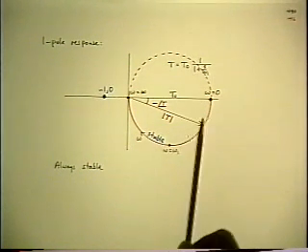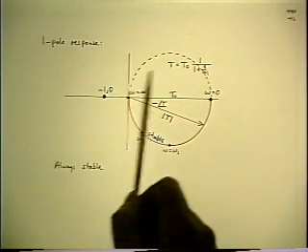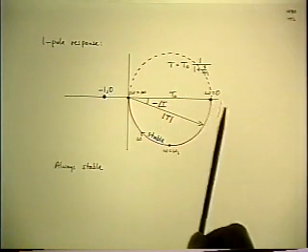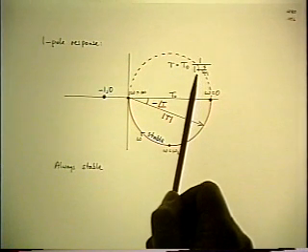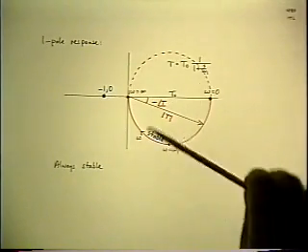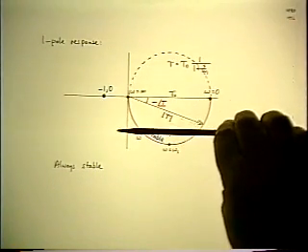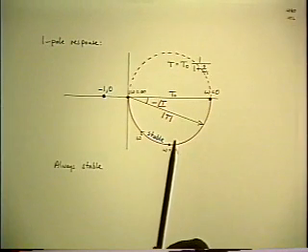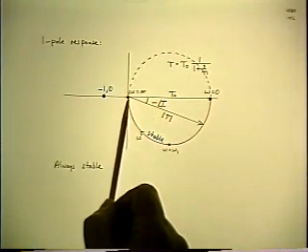Now, Nyquist said we have to draw the contour not only from frequency 0 to infinity, but also from minus infinity to 0. And that's easy, because the only difference is the phase angle is reversed for negative frequencies. Magnitude stays the same. So the negative frequency contour is simply the vertical inversion of the positive frequency shape, and since that was a semicircle, the full contour is a full circle in this case. The negative frequencies, of course, is what closes it.